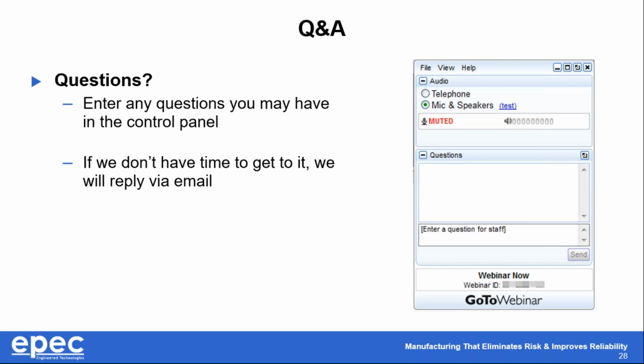Next question is, our team needs an inexpensive cable product. Of the cable types Epec presented today, what's your recommendation? That's a good question. We recommend finding the best readily available wire that meets your project's needs. So finding the best is a relative term. As we said before, I definitely start with the temperature and voltage ratings of your project. Next, you're going to want to study the material of the jacket and make sure that the environment you're using the cable in will be okay with that type of material.